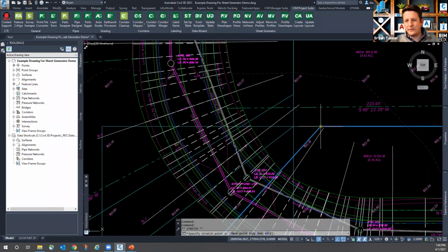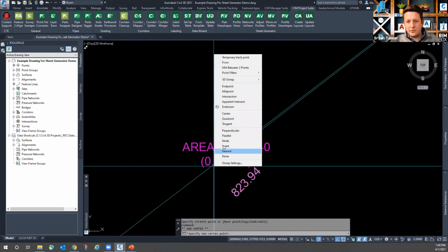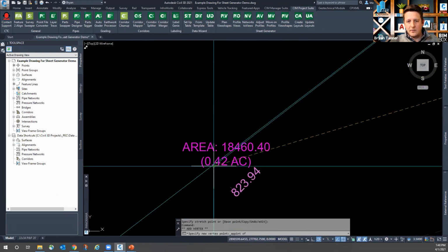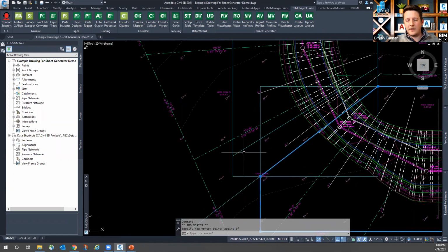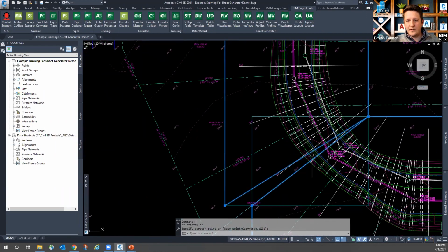I can adjust. These are effectively just polylines that represent the information that we want to trim. I can add and remove vertices. Those vertices can be manipulated and additional vertices created to more accurately represent where all of these intersections are taking place. And they don't have to be rectangular shapes.